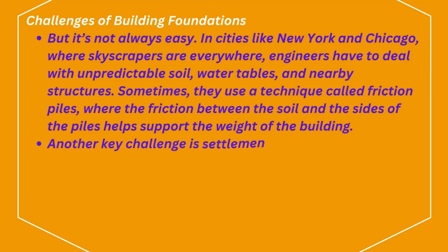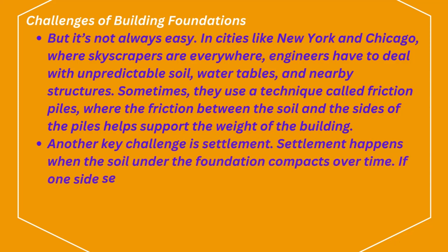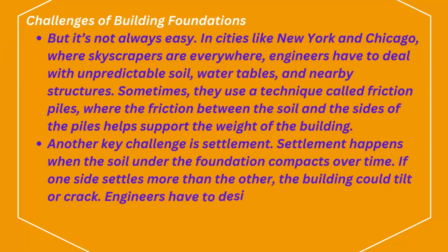Another key challenge is settlement. Settlement happens when the soil under the foundation compacts over time. If one side settles more than the other, the building could tilt or crack.